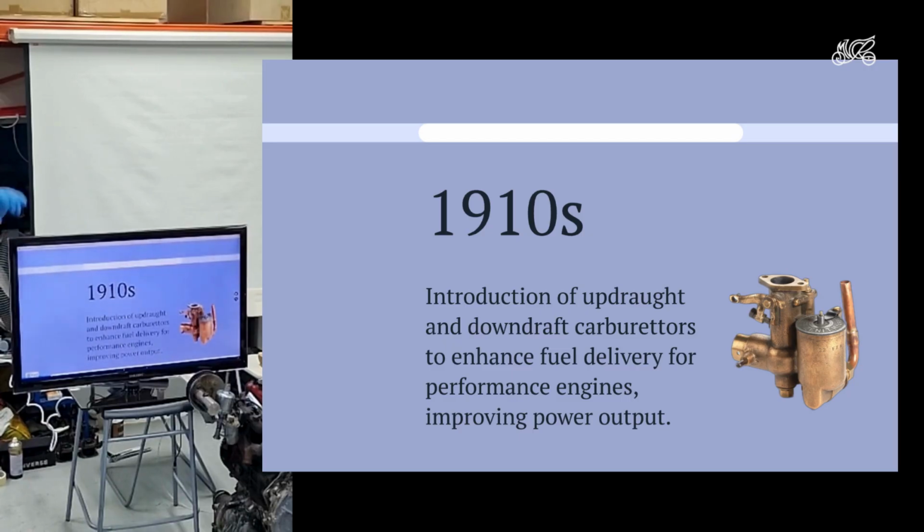You've got a choke, an area of smaller diameter. You've got some form of fuel supply sitting in that area. And as a result, the fuel comes out. And the great thing about that is, as the engine speed changes, the airflow increases, the pressure changes, and therefore it's somehow compensating. So this is the great breakthrough, was exploiting the Venturi effect, because then you had a thing that as the airflow changed, the fueling would change, and that's what you want, right? So basics of a carburetor.